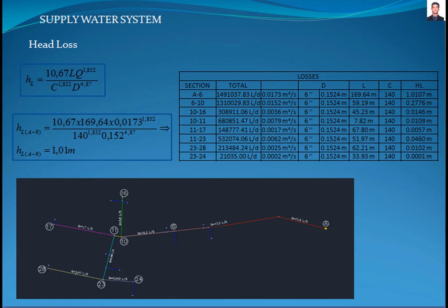figure. Now we are ready to select the pipe material, calculate the diameter required by the system, its velocity and losses for the pipeline. It's a good practice to make the design with 3 different types of diameters and materials to select the best option in terms of performance cost for the system. In this tutorial, the system just will be designed for steel material, according with the American Water Works Association M11 standard. First, we are going to calculate the diameter required and losses generated by the diameter chosen.